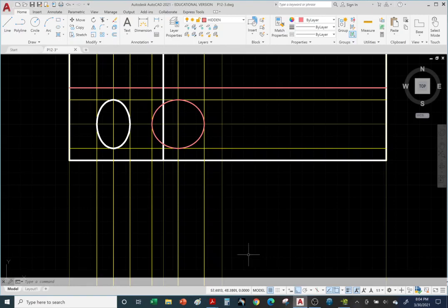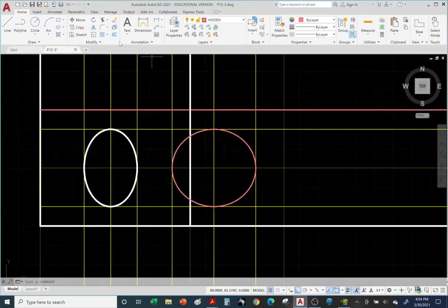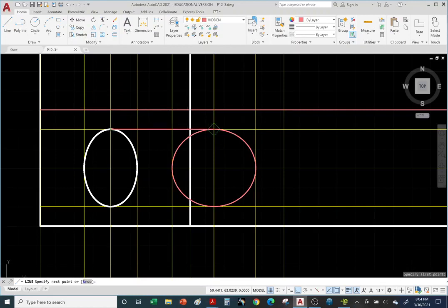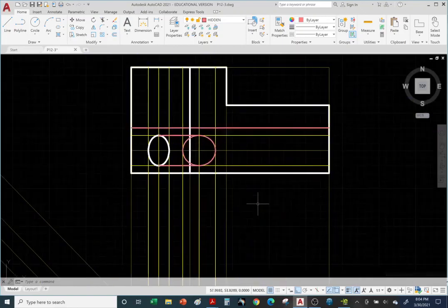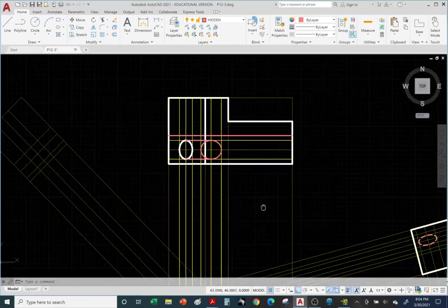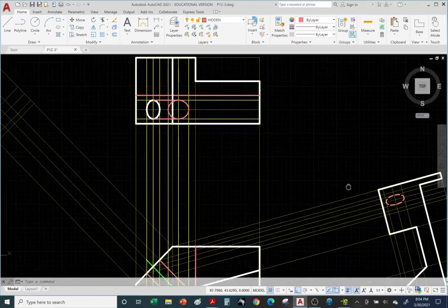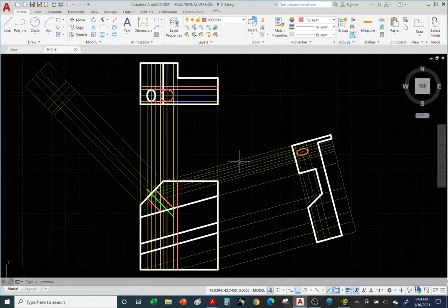All right, back to AutoCAD. Let's connect the ellipses with red hidden lines. They're hidden because we can't see them. Right click enter. Okay, and bottom quadrant, and right click enter, and there we have it. Ta-da! Done. All right, so let's cheat and take a look at the answer key before we move on to the auxiliary view on the right. I think we have everything so far.